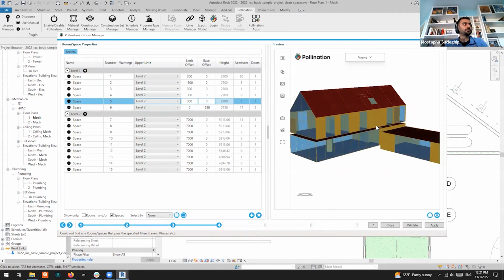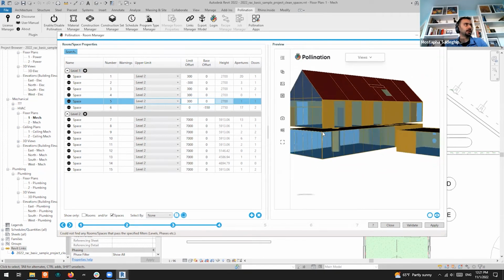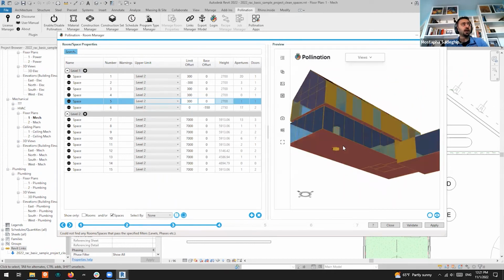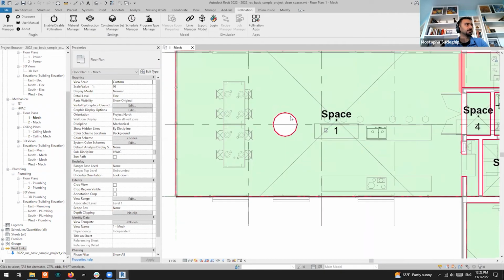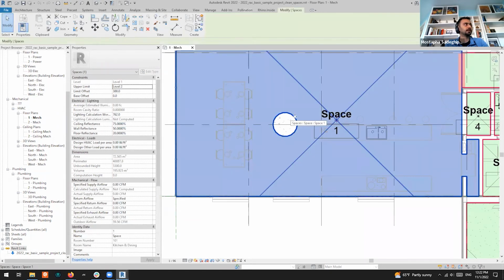The things that we can fix is, because the rooms are here, we can basically overwrite the height that I did and fix this gap. The thing that we cannot fix is this column here in the middle, because I don't have access to this column, right? It is in the linked model. I cannot right click on it and say it's not room bounding. And this is again going back to the reason why we want to add more repairing workflow.